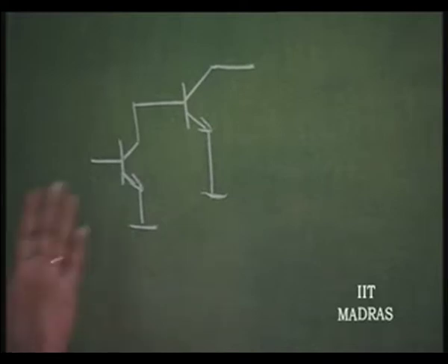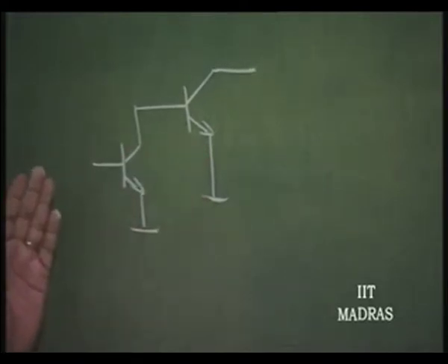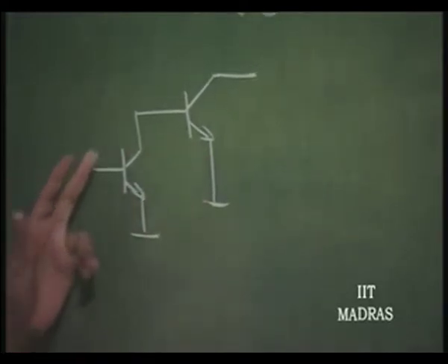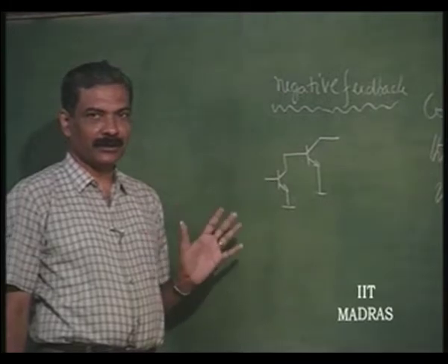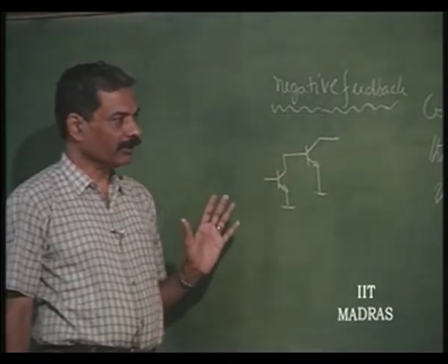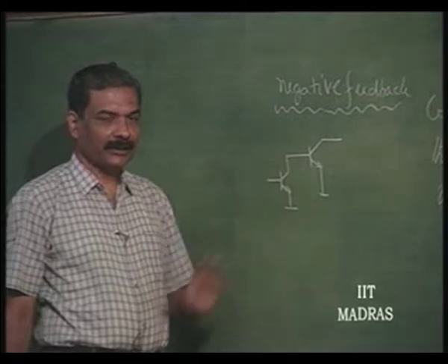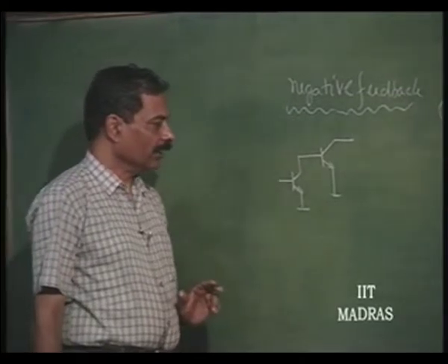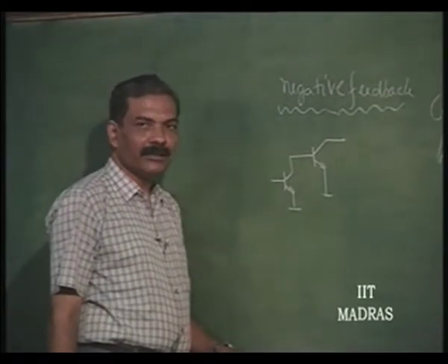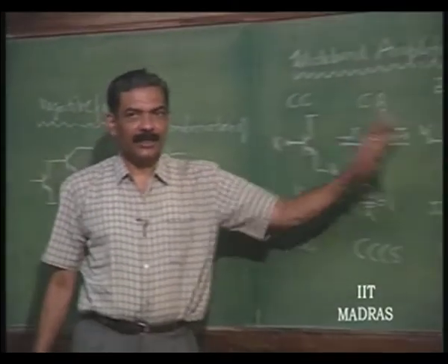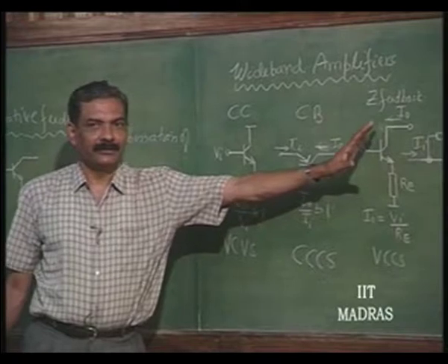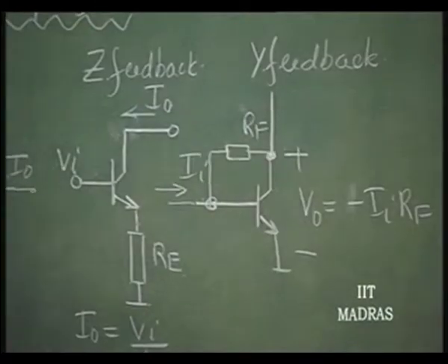Now, the moment you have two transistors, you have three time constants like input, intermediate, output, and therefore, it is likely to go into oscillations because of the three time constants, and therefore, it will need compensation, whereas these do not need any compensation and they retain their wideband structure even while cascading.